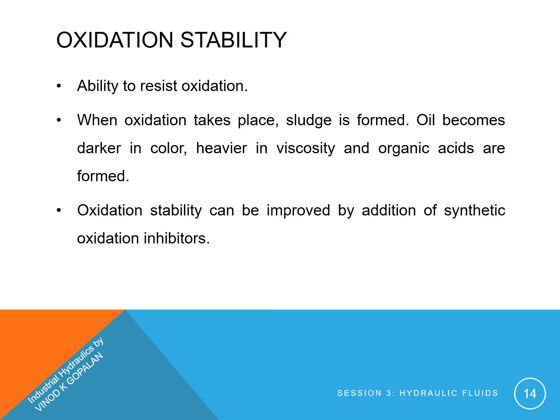Next is oxidation stability. It is the ability to resist oxidation. When oxidation takes place, sludge is formed. Oil becomes darker in color, heavier in viscosity, and organic acids are formed. Oxidation stability can be improved by addition of synthetic oxidation inhibitors.